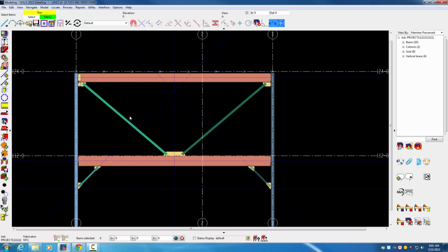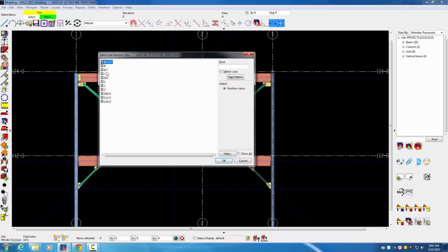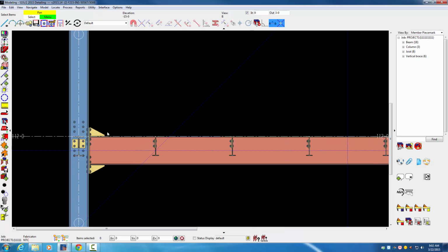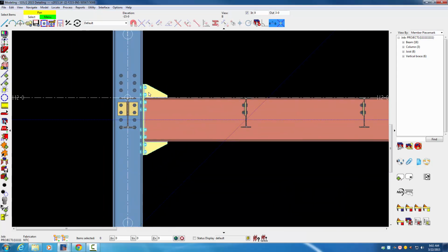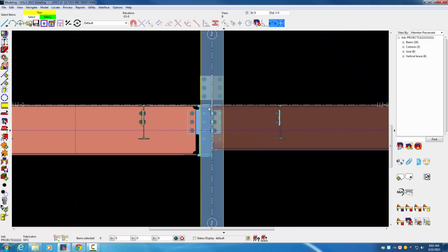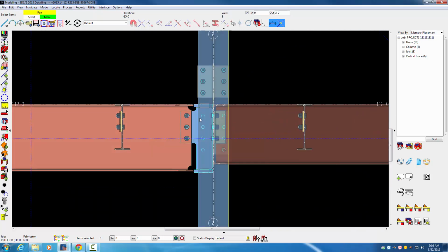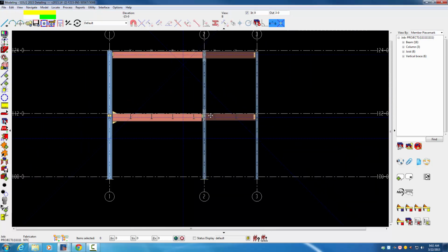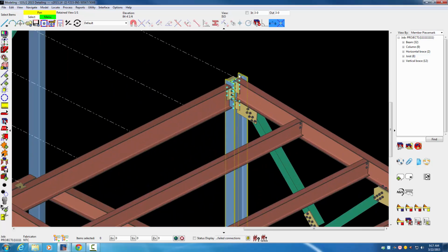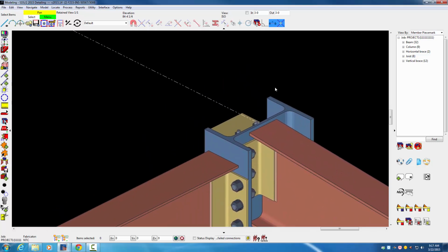So now let's go to grid line B, and that's on your sheet S4. And all we're going to really look at there is, again, we looked at this previously on that moment connection here. We had that working on the other end. We had the welded moment working. Okay, the final thing, if you remember, we had this bar joist here, and the connection I said was incorrect.